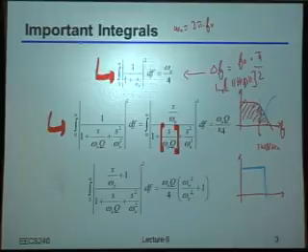Okay? The only other thing I'll mention is that if you look at this form here, this is a slightly more generic second-order transfer function, where I now have a zero as well. Turns out you can actually derive this from these two expressions here. Because notice that something with no zero and something with a zero at 0 both evaluate to the same expression here. So if you wanted to figure out what this was, you can just take this and add it to a scaled version of that, and you'll end up with exactly this expression that I have down here.